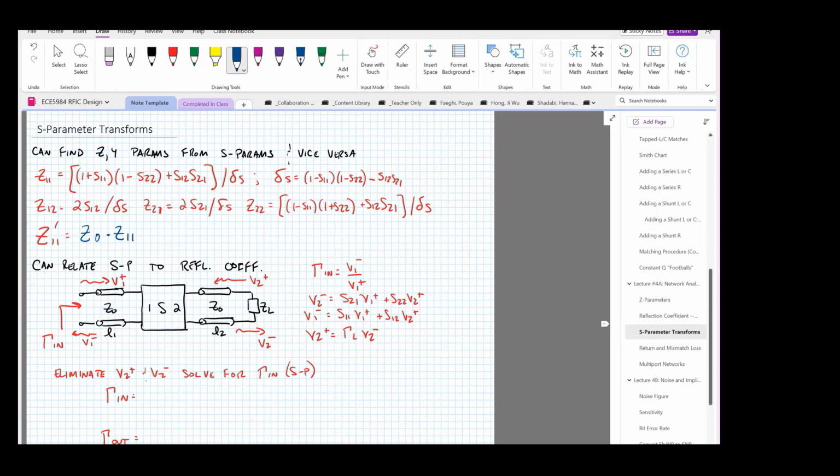So I have a question here. If we have 50 ohm output impedance, then let's say we have a common source amplifier which requires high gain for high impedance, how do we connect it? So we'll look at a common source amplifier. If we look into the gate of a MOSFET, the gate of a MOSFET is always highly reactive. And so we have to synthesize a real impedance. We're going to do that with negative feedback, actually. So we'll show you how to do that in a bit. But yeah, we have to synthesize a real impedance.